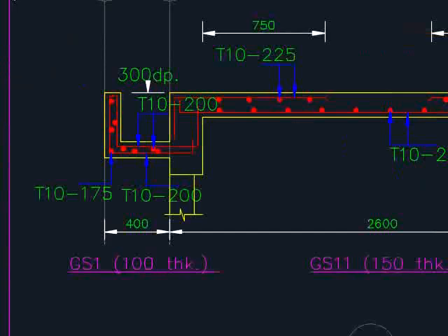As for the reinforcement bar, it can be something like this, especially for this layer of the reinforcement bar. It needs to be continuous. In fact, for this one, the better design will be this going to the end of the member and going up, while at the same time you have a member here going up on this side. You swap the positions, but you have to provide additional reinforcement bar in order to ensure the corners here.